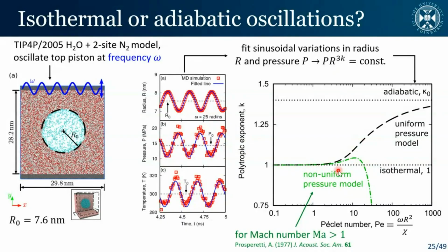And you'll see that for nanobubbles, this is specifically for nanobubbles. For larger bubbles, this peak is closer to its adiabatic limit. For nanobubbles, we shouldn't really expect much more than isothermal behavior. However, when we ran the MD simulations, we see completely non-trivial behavior and what looks like an adiabatic maximum, which is currently unexplained by these theoretical models.